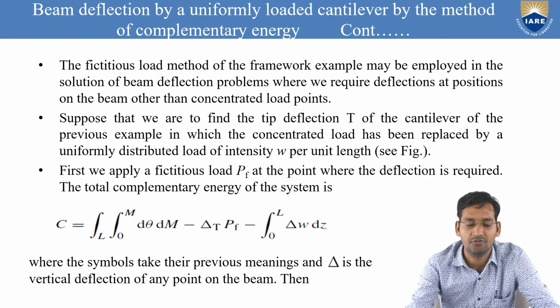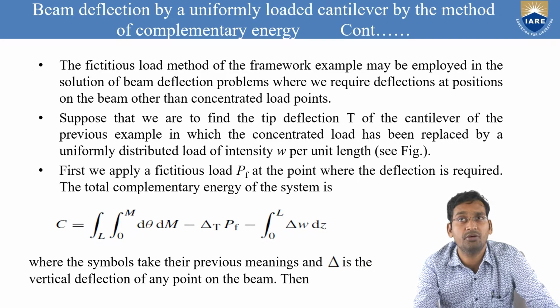So let's see. The fictitious load method of the framework example may be employed in the solution of beam deflection problems where we require deflection at positions on the beam other than the concentrated load point.